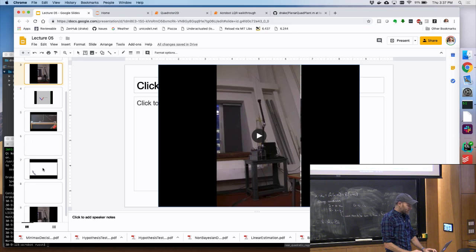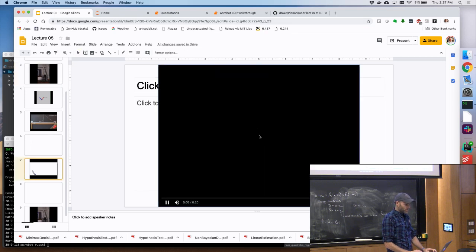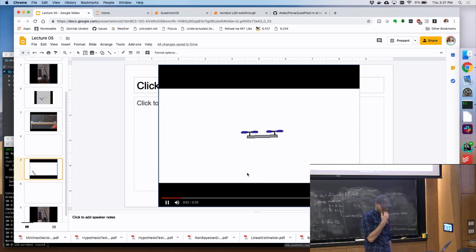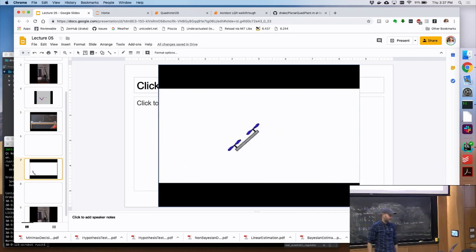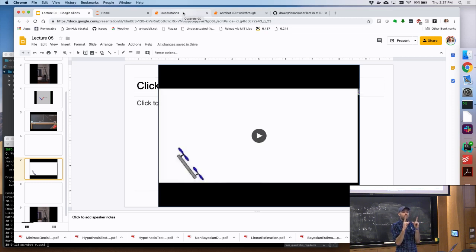Okay, exactly the same stuff is going to work for quad rotors. So this is my Python drawing of a quad rotor, which you'll be able to play with. This is the planar quad rotor. So again, now I've got a fixed point where u is not 0, because my nominal operating point is applying some thrust going upwards, otherwise I'll fall down. But if I just take the equations of motion of that system, linearize it around the top, call LQR, you're done.